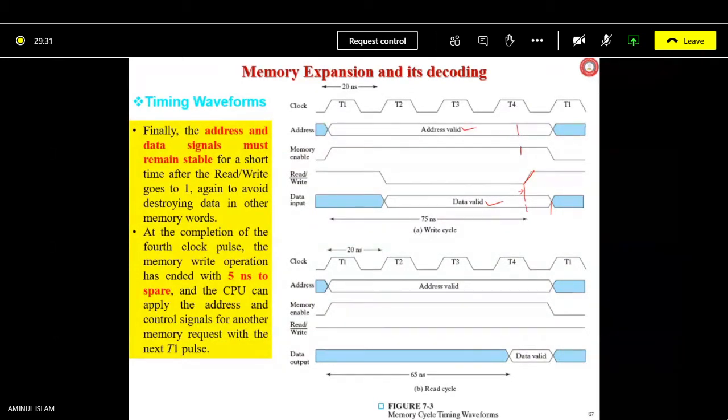So we have discussed the setup time, propagation delay, etc. Can you remember why at all we have to keep data valid for some time? Yes, so that all these requirements of the storage elements are satisfied: setup time, hold time, propagation delay, etc.